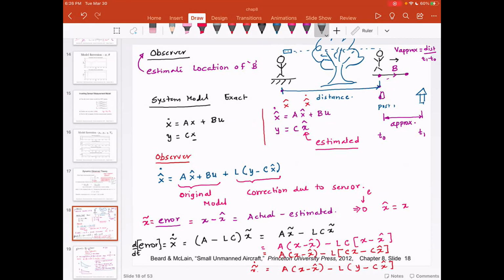If you cannot observe, or if you have partial observation, there are different excellent schemes for estimating the measurement. But let's start with the very basic. The very basic idea is I don't have a direct way to get the measurement value, so I'm going to use an alternate way to get the measurement, and the way I do that is by means of something called an observer.